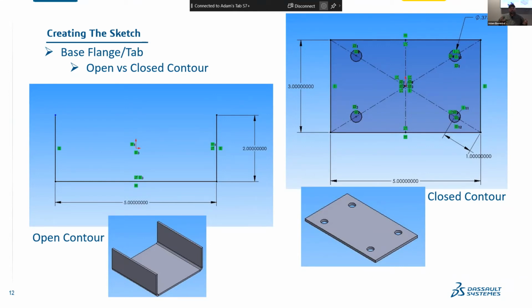All right. And again, that's up to you because as I'll show you here in a minute, when we get into the flanges, how do you build those flanges? Because now if I take the closed contour and I put 2 flanges on it, what did I just do? I created at least 1 or 2 more features that can possibly even slow down my model, right?